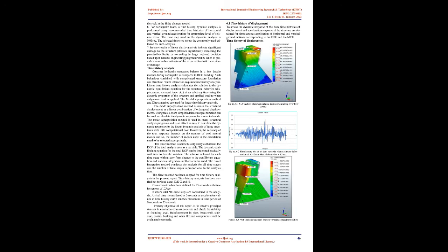2. Concrete and foundation rock can be modeled as elastic, homogeneous, and isotropic material. 3. Hydrostatic pressure acting on the dam is represented as surface pressure acting on the water face of the model. 4. The water-dam interaction has been modeled by the added mass concept recommended by Westergaard.